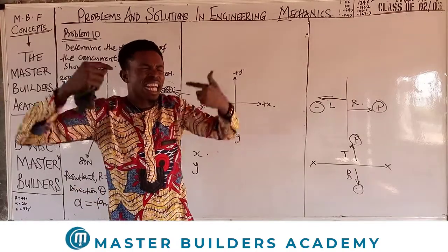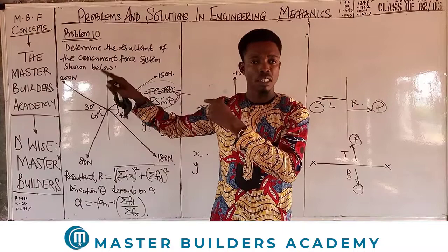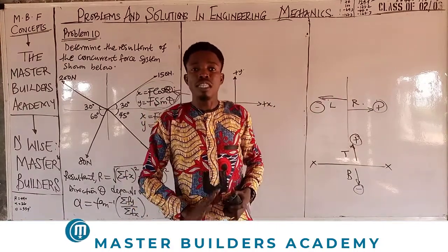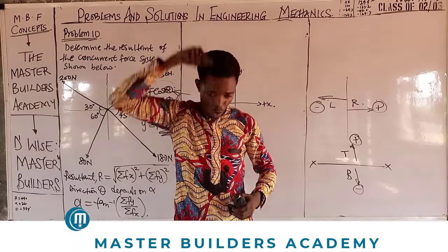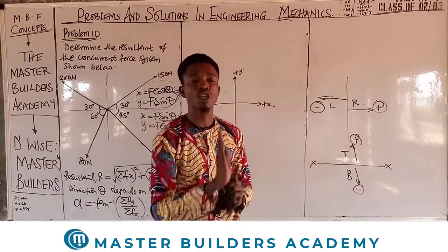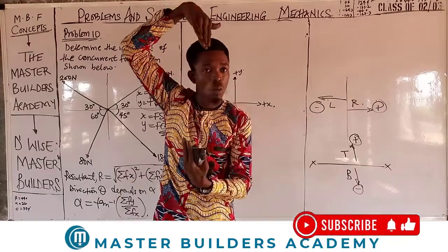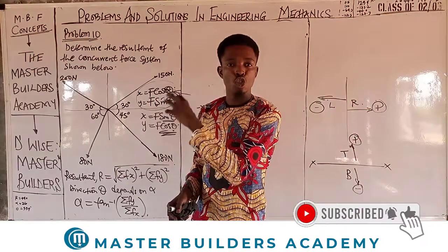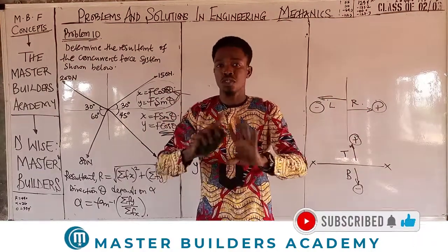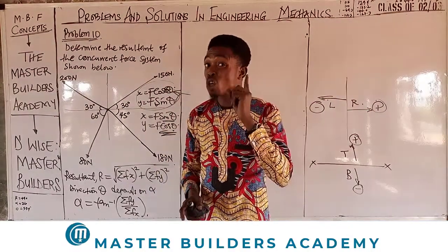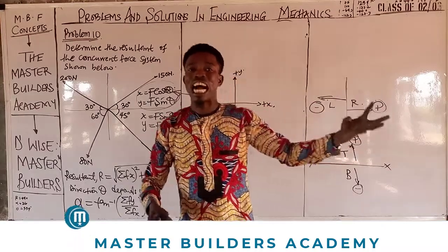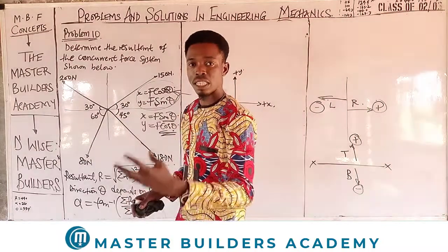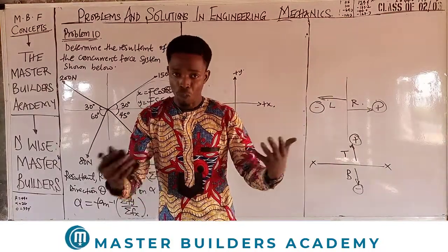Now, when you are resolving along the y components, guys, you need to identify if the direction of the force is upward or downward. Clear? If it is upward, it's positive. If it is downward, it's negative. If you understand this concept, you will not have issues with resolving concurrent forces or a force system. So these are the two major keys you must identify: where the angle lies and the direction of the forces. If you understand this, the analytical aspect will not be a problem.